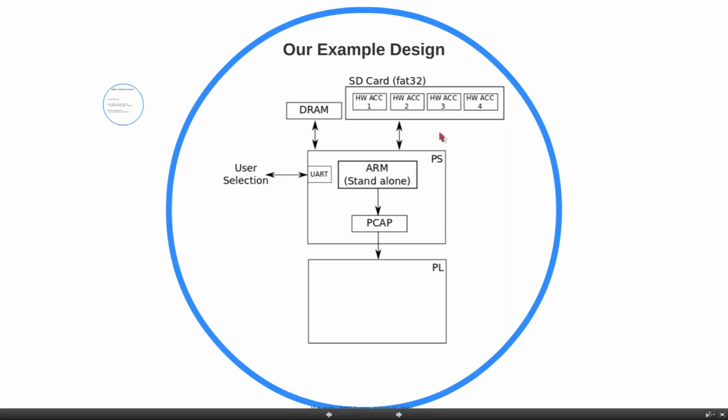You want to be able, at each moment in time, to read one of these bitstreams, copy it to the DRAM, and then program the PL with that bitstream using the PCAP component. This is what our example is going to show.